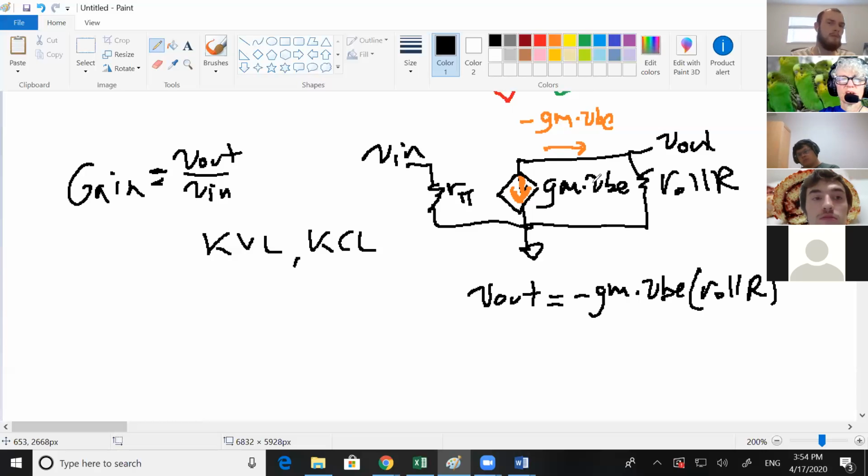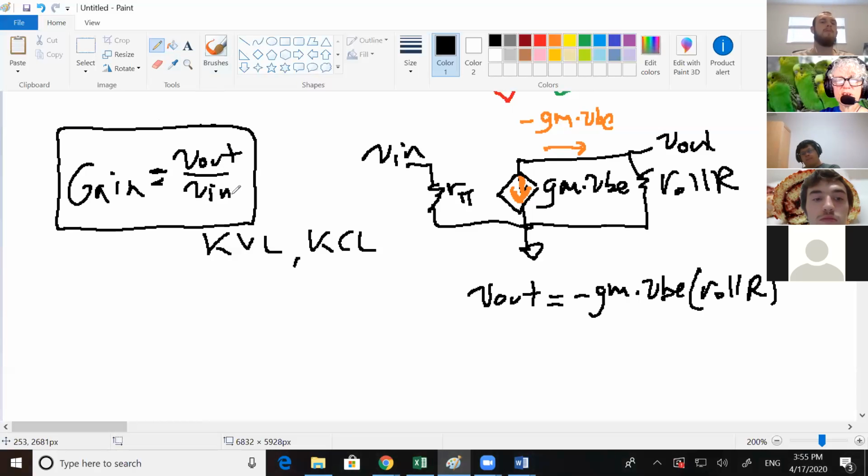When you do that, a good thing to do is go back to your original equation, and you want V out over V in. So you need V out and V in your equation. V out, that's in the equation. Okay, good. GM, that's not a voltage or a current, so we get to ignore that. VBE, that's not in that equation. So we need to get rid of VBE somehow.